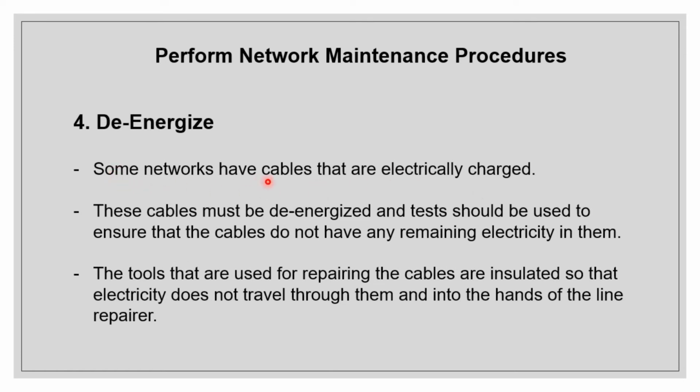De-energize. Some networks have cables that are electrically charged. These cables must be de-energized, and tests should be used to ensure that the cables do not have any remaining electricity in them. The tools that are used for repairing the cables are insulated so that electricity does not travel through them and into the hands of the line repairer.